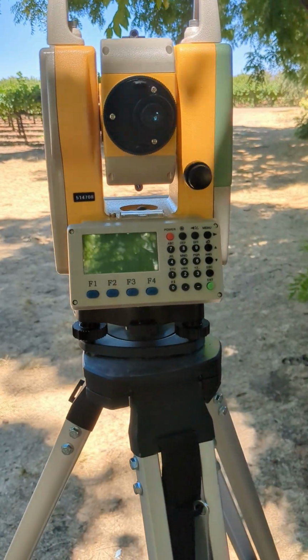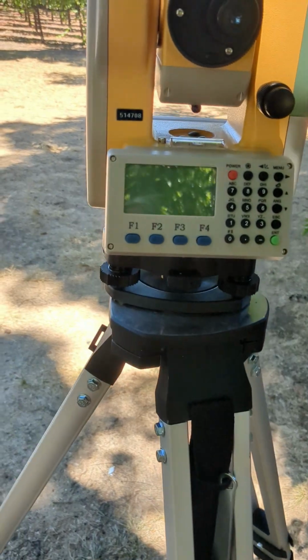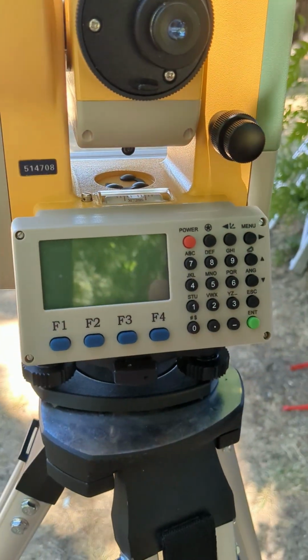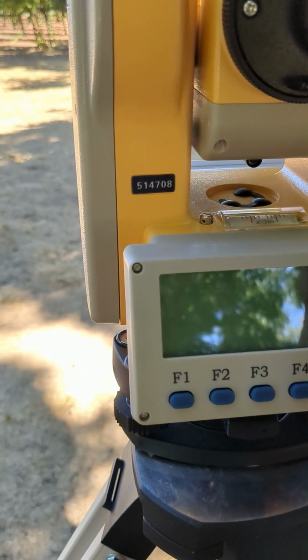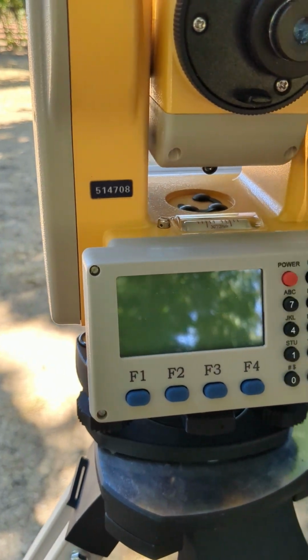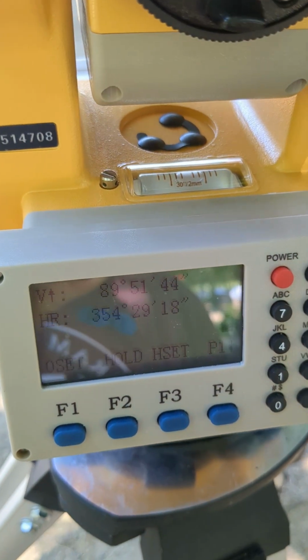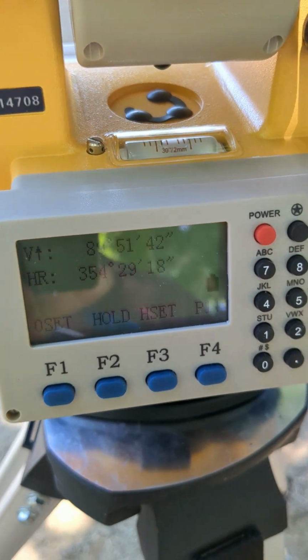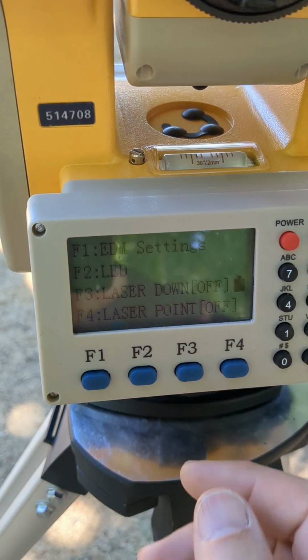Okay, we just approached the total station. The first thing we want to do is level it. To help level it, it's nice to turn on the laser beam that points straight down. So I'm going to turn on power. The power goes through a little self-test, and then I can turn on the laser, and F3 says laser down.